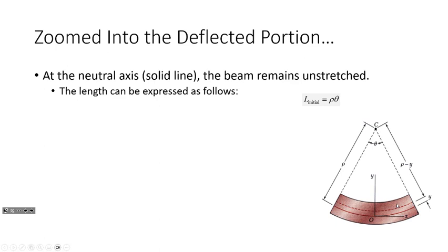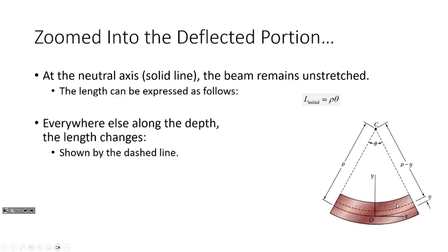Do y'all remember that? That if here's the radius and this angle is 20 degrees, the radius times 20 degrees in radians will tell you that curved length. Okay. Well, I propose that that formula only works along the neutral axis, along the centroid of that beam.